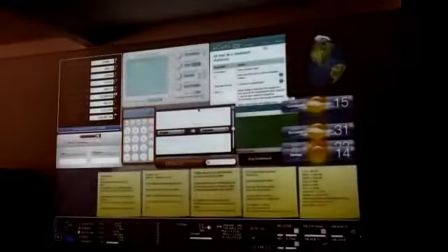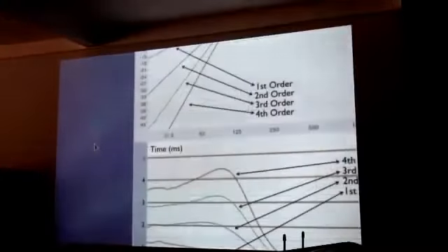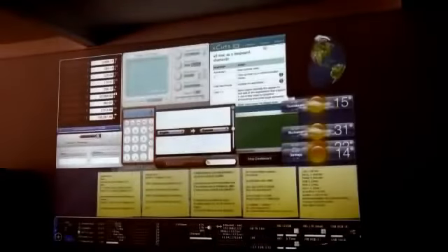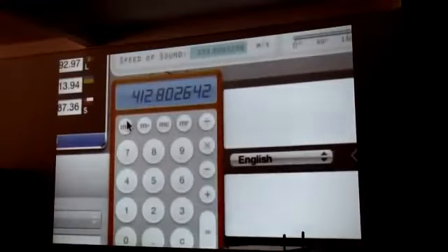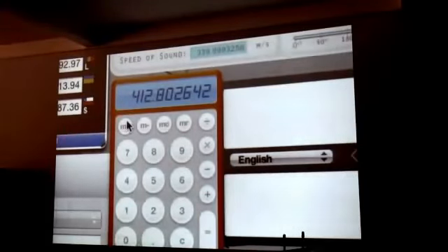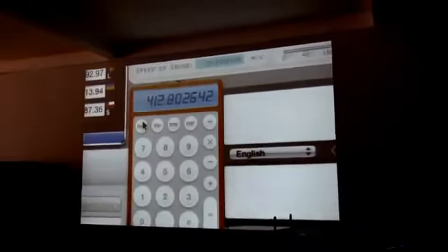So, if we need to delay, according to this graphic, 4.3 milliseconds, 4.3 divided by 0.010141666, we need to add to the processor 412 taps. After doing 412 taps, all frequencies will be delayed the same time. This is what FIR filter is doing.